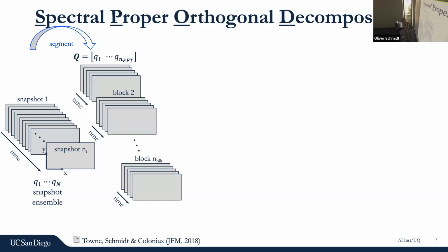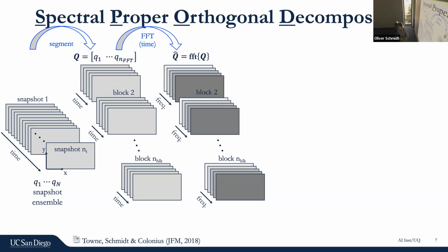Doesn't matter. The first thing is we want to go to the frequency domain. But first, we're going to segment this data. We're just going to chop it into segments, and these segments can overlap. Let's say we have 10,000 frames. Make each of these 256 long and make them overlap by 20. Pick a number, right? So then we have many building blocks.